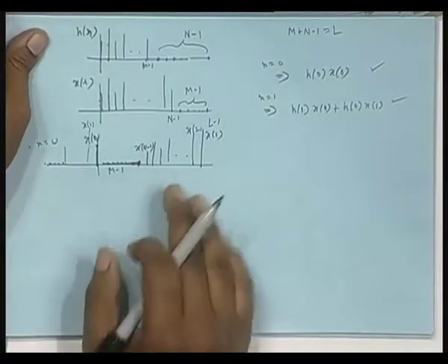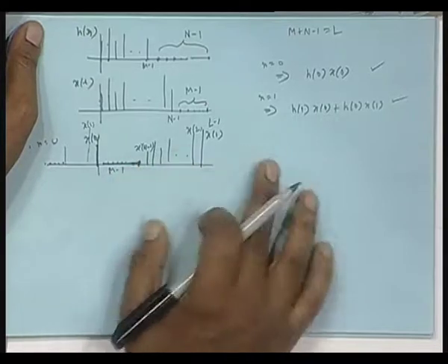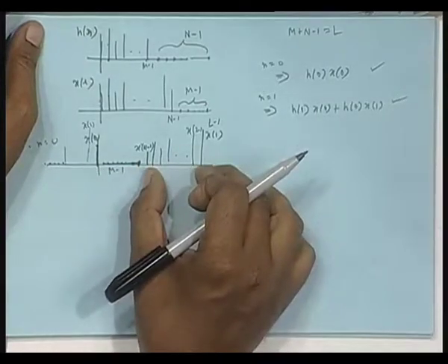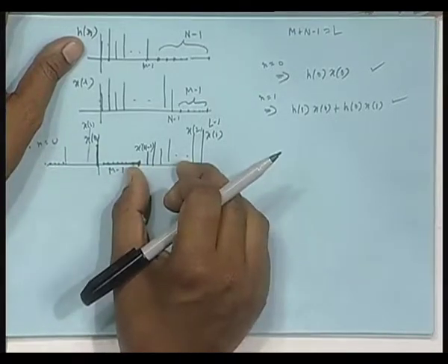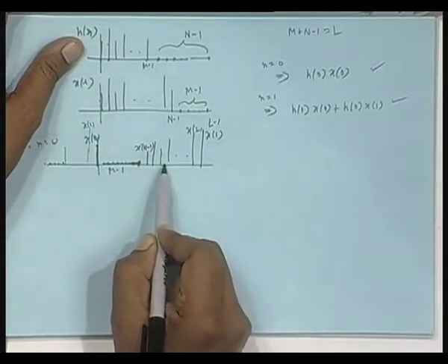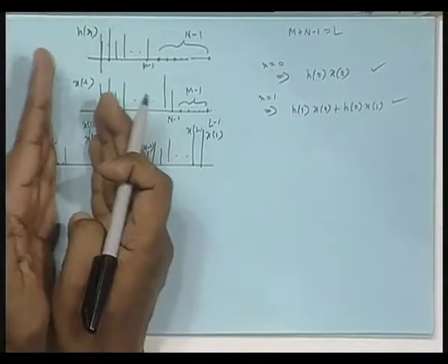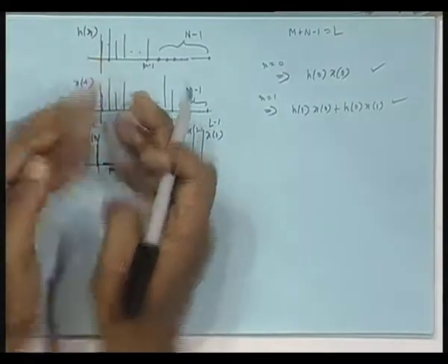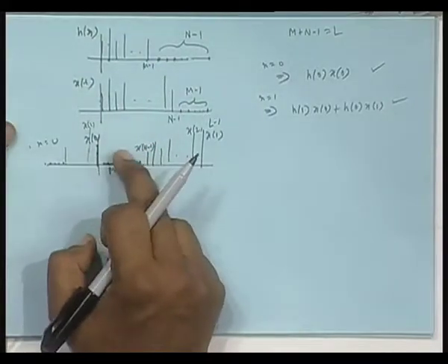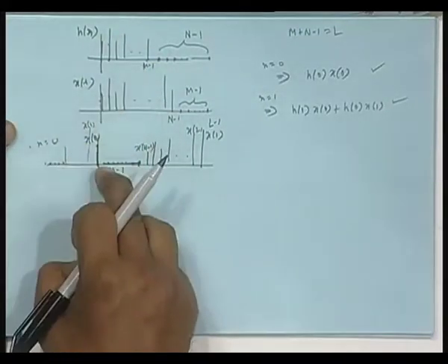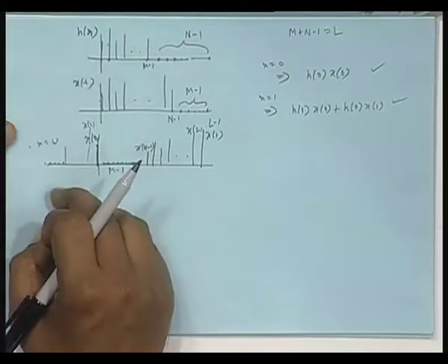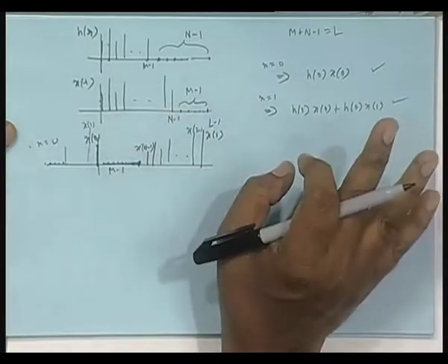As I go on shifting, some data will go out, this 0 keeps moving, 0 comes to this side and data comes, as long as this data comes here, no problem. They will multiply, like x 0 will move further to the right below h 2, x 1 below h 1, x 2 below h 0, you get convolution result at 2.